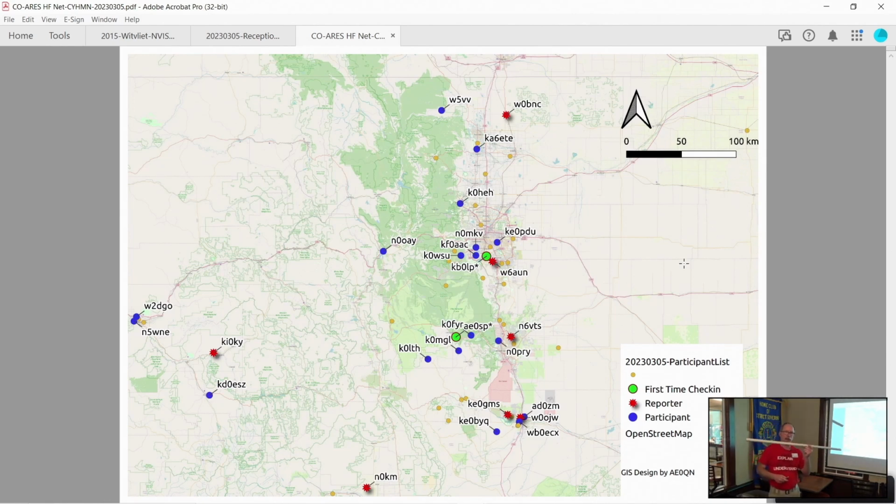Dipoles cut for the bands, so you're talking about 3 different bands or 3 different dipoles, or a dipole with clips or traps so you can work on multiple bands. For my work, I was gearing towards how do I put a bunch of junk in my car and drive out to a canyon and set something up by myself and work all 3 bands without having to run around and clip and unclip things to change bands.